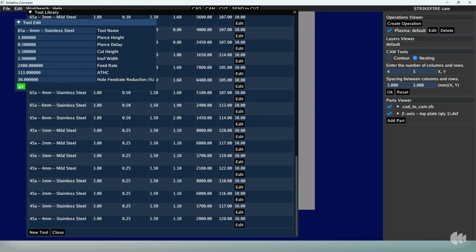But all your circular profiles, it will slow down below 40mm. If they're greater than 40mm diameter, then the machine will cut at its normal speed because they typically don't have the issue of smaller holes.